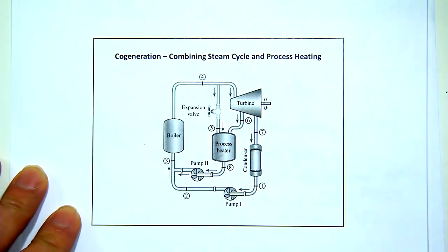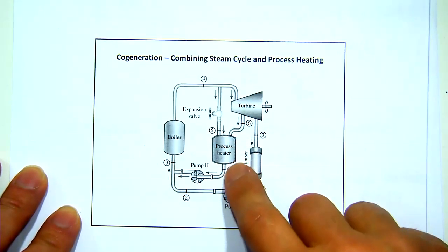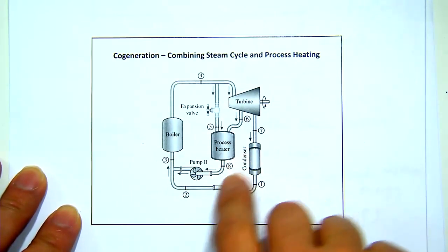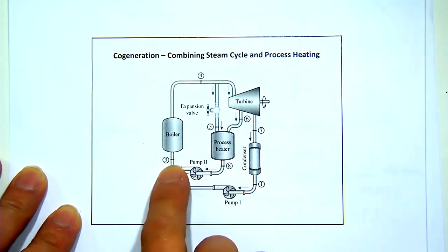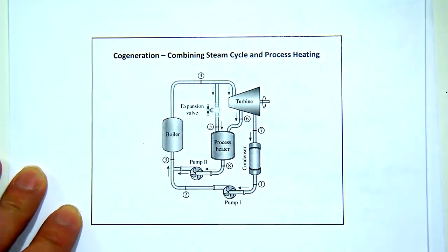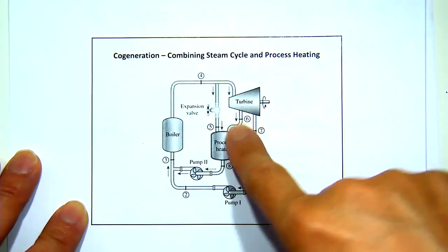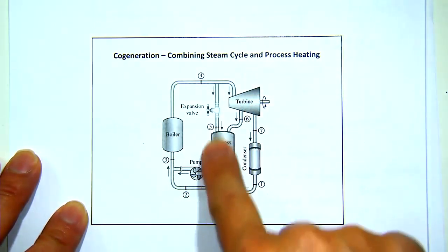You're going through the heater to heat the other thing that you want to do, and then after that, the steam is condensed to water, and then goes into the pump to the same pressure as that going through the condenser, and then goes into the boiler. So to some extent, it's similar to the feed water heater that we just saw. So we have a partially expanded process, but this is not being heated.